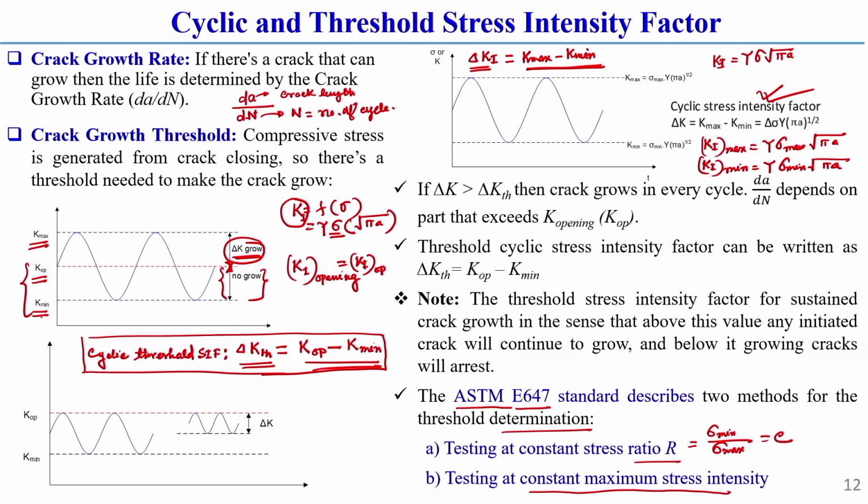So, in detail, here we have written the threshold stress intensity factor for a sustained crack growth, in the sense that above this value any initiated crack will continue to grow, and below it the growing crack will arrest. These are the things you should keep in mind.